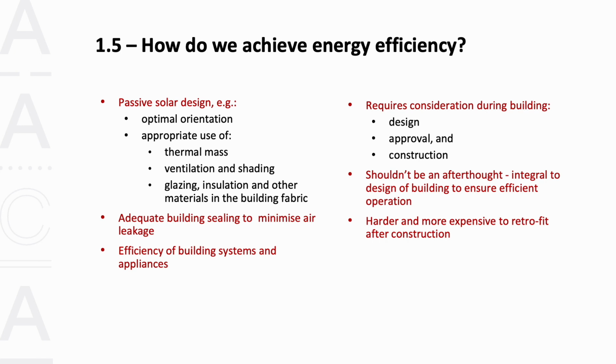Glazing that's appropriate to the climate is also important, considering the orientation and position as well. This involves considering more than just the type of glass and frame. It extends to the size of the glazing or the windows in these different walls. In southern latitudes, large windows on the north that get winter sun can help to warm the building during the day, and at night if there's sufficient thermal mass in the house. In the same situation, windows on the southern side of the building should ideally be kept smaller, as they act as a source of heat loss regardless of the type of window used. That also includes its glazing in the system.